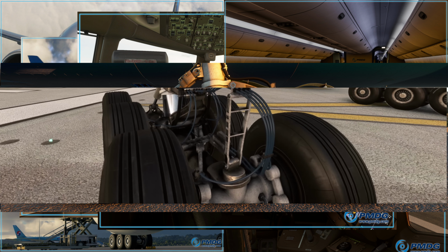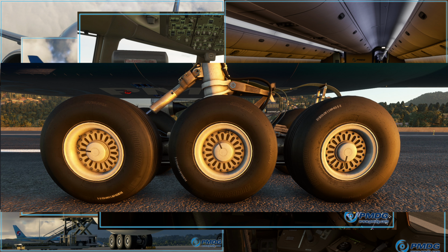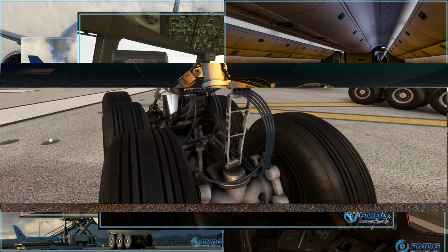You gotta imagine that the entire gear over here is longer than a typical car that you might have in your backyard, and if you are turning the entire plane, the forward and the aft wheels would more or less be skidding across the ground. So for that reason, the aft two wheels actually can turn a little bit to provide a little load relief on the entire system.